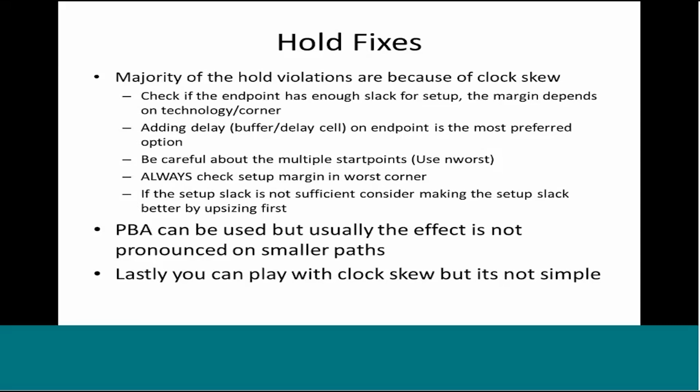The worse the ratio is, the more difficult the timing fixing is. Why? Because a small delay in the fast corner will give you a large delay in the worst corner, and you cannot fix the timing. The better the ratio, the easier it is to fix timing. This ratio is better for high drive cells and for low VT and standard VT cells, and not so good for high VT cells. Similarly, this ratio is bad for low drive cells.